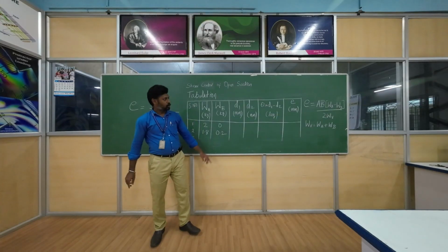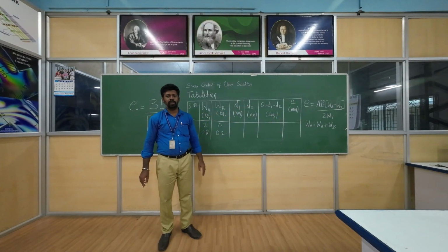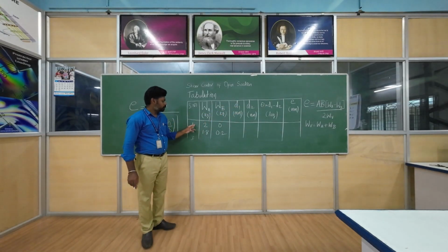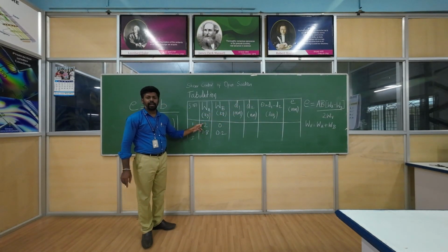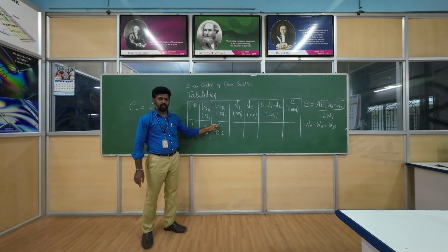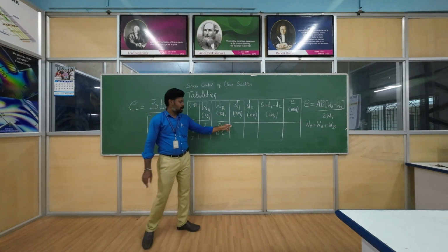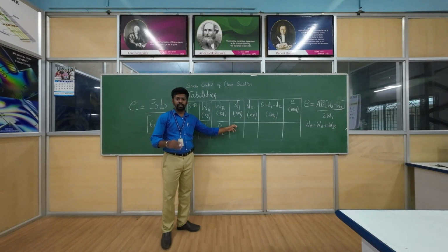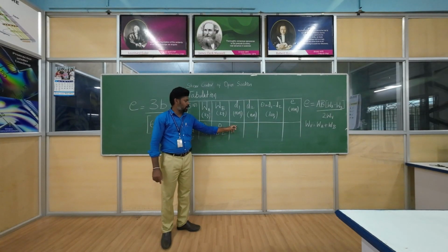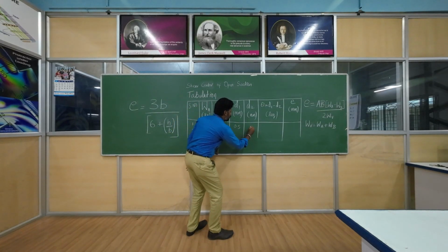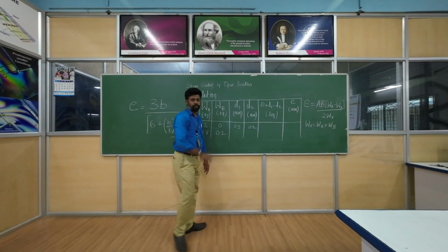So now already we defined that distance between A and B is 160 mm. So you can see for the first reading I am applying 2 kg at the point A and I am applying 0 kg at point B. There is no load at point B. So for this set of loading, I will be getting the deflection which was noted on the top of the beam, D1 and D2. So I get some kind of 0.5 and 0.2 something I get.